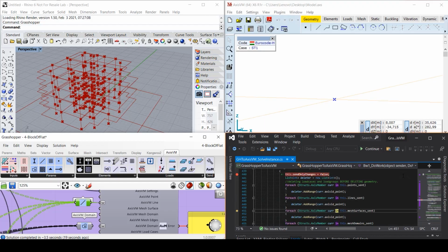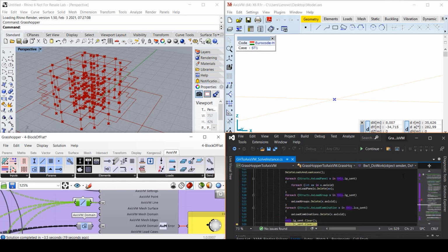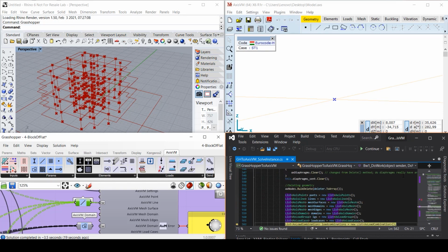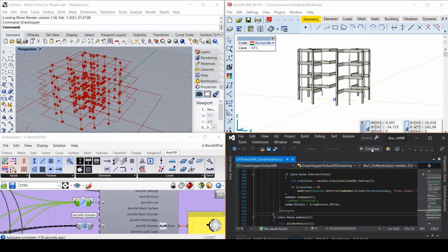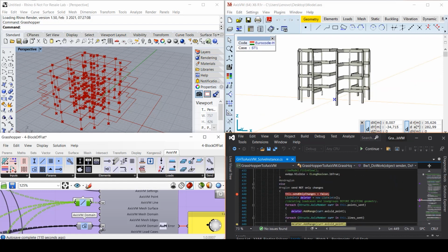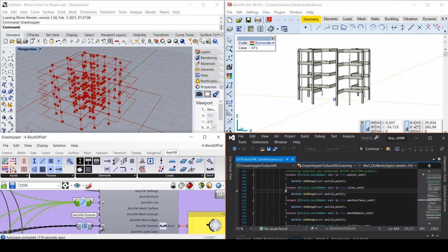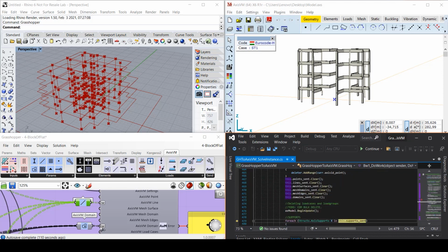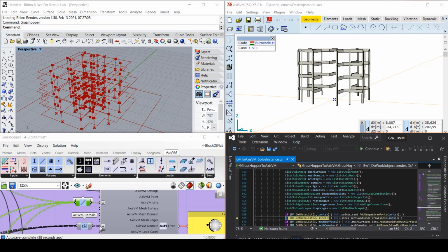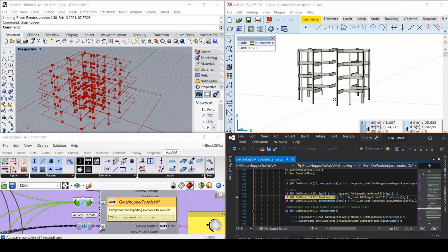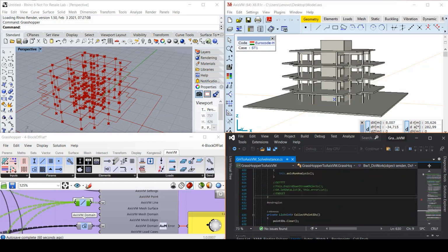The plugin is developed using the C# programming language in .NET 4.5 environment. It communicates with AXISVM via COM server, the so-called API, Application Programming Interface. When we transfer data to AXISVM, hundreds of commands are executed in the background in a split of a second. The video illustrates what happens if we transfer some line elements and then some domains of a 4-story reinforced concrete building.